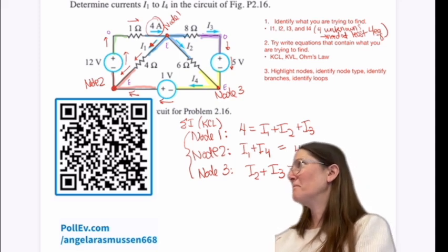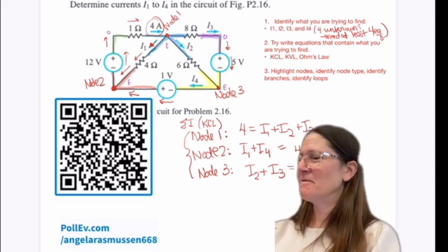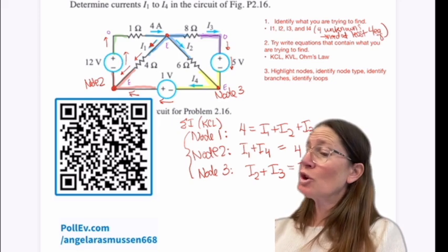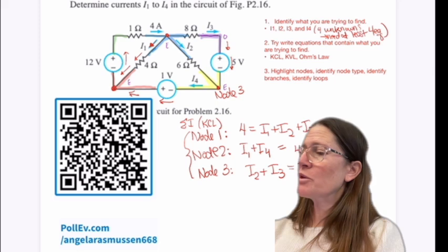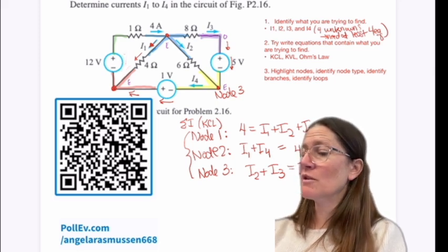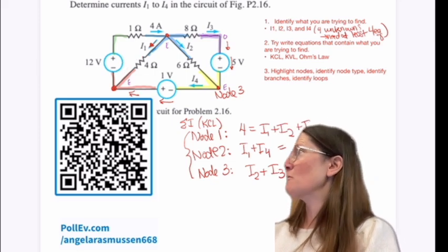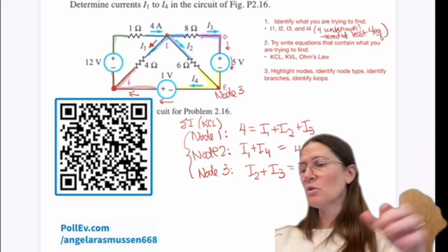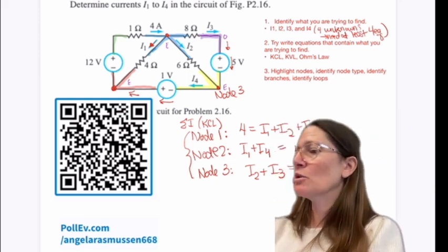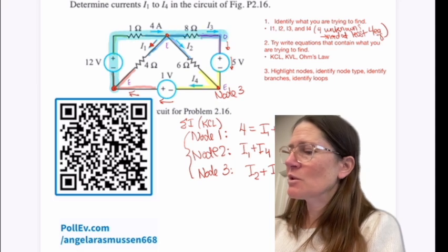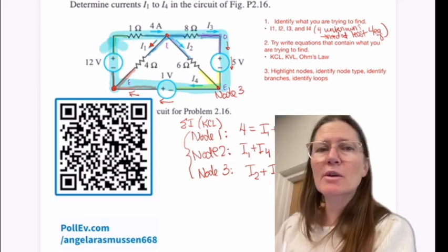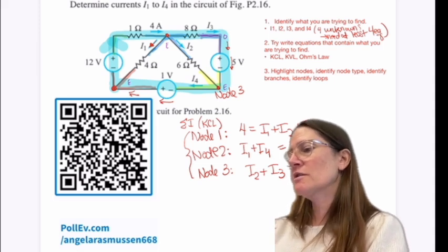Yes, thank you. Using KVL for the top left triangle loop, since you have all of the information needed to find the I1. Okay, so taking a loop through elements that have the most known information is going to be what you're aiming for. So as Cole mentioned, that's going to be going through the 5 volt and the 1 volt, which is like my outside loop. So again, that was going to be this loop that goes through all of that. And depending on which way I want to go, I'm going to pick going in this direction.